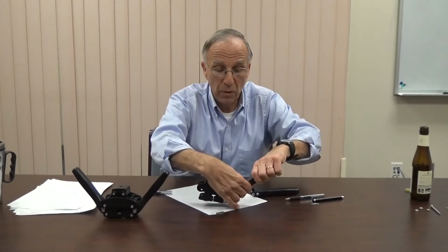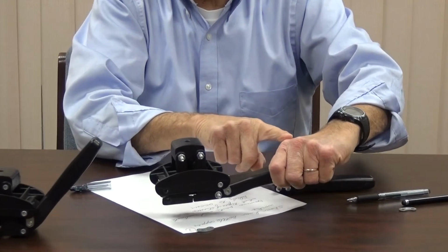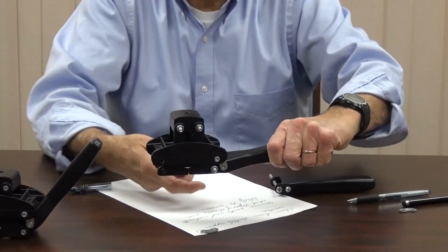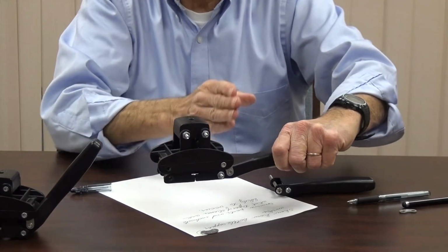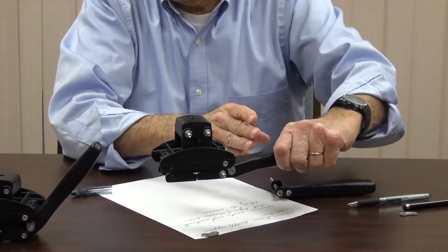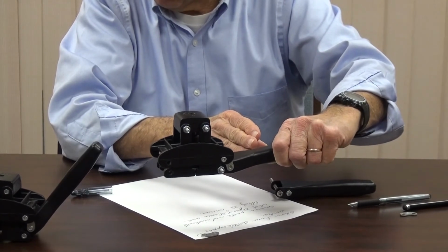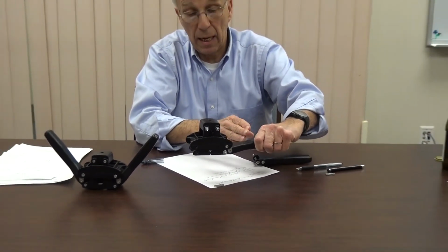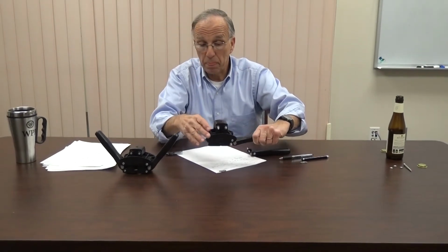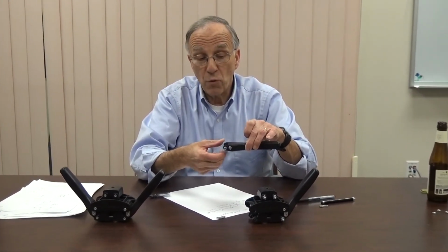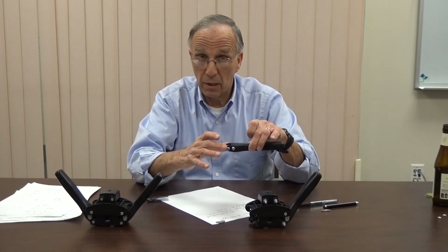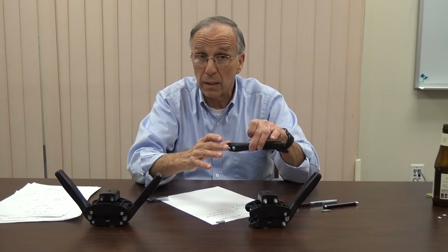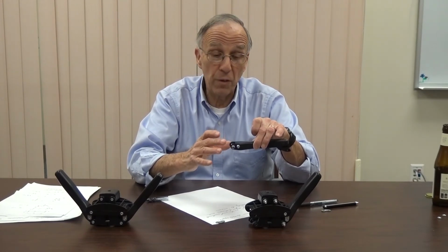Now, the other thing we can look at is when this is turned around, when this is down like this, it acts as a beam that's pivoted about here. So I'm pushing down on this so I can generate at this cross section both stresses due to a moment, which would vary with position according to our previous discussions, and also there would be shear forces. So even a device which has relatively simple geometric design can have a variety of different kinds of stress calculations associated with fully analyzing it. That concludes our video on stress analysis.